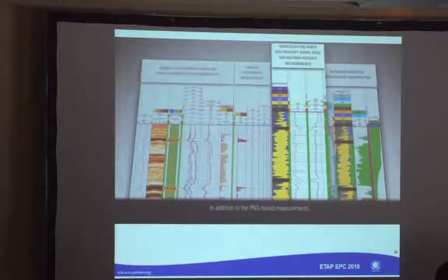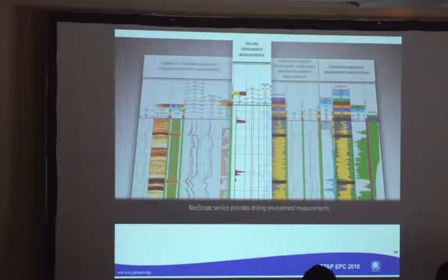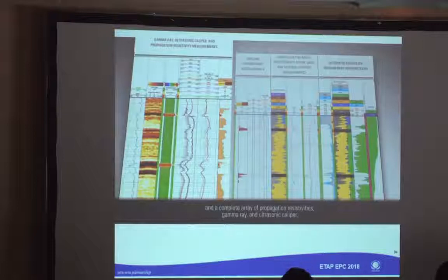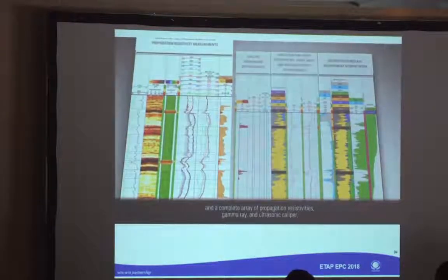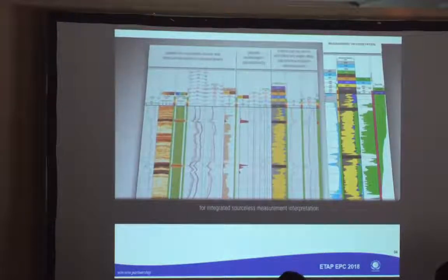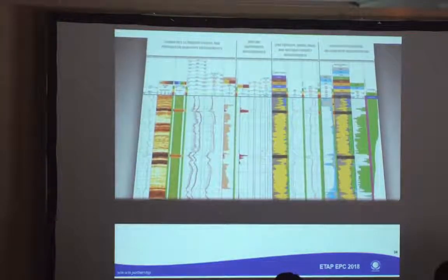So we have all the open hole logs, in addition to all the drilling environment measurements, as well as gamma ray, ultrasonic caliper, and propagation that we'll see a bit later. All these logs will enable us to perform a real-time petrophysical evaluation.